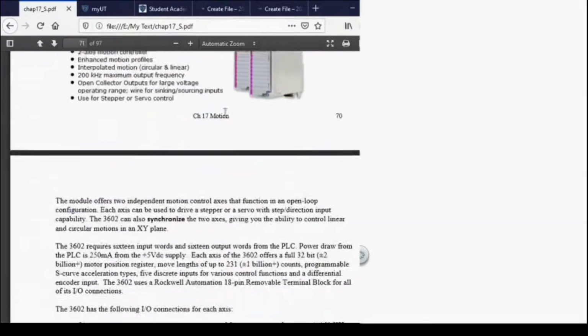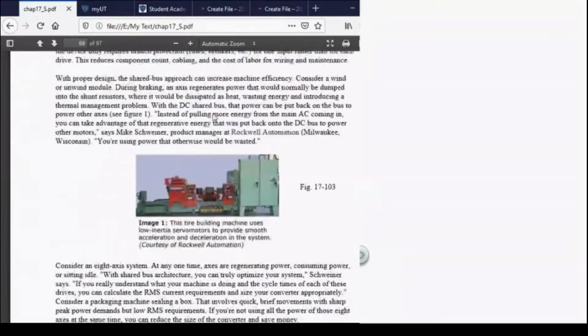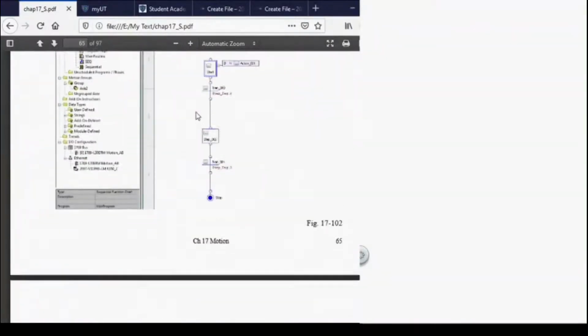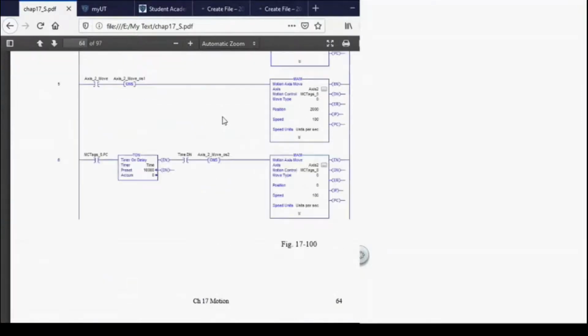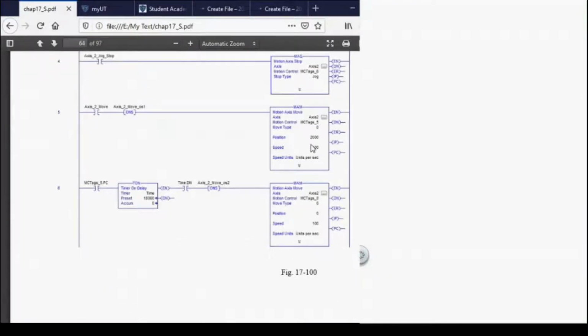And some of those bits are rather deceiving, because the done bit doesn't mean you're done. It just means that it acknowledges that it started doing the action. The IP means it's in progress, and PC means that it's complete.